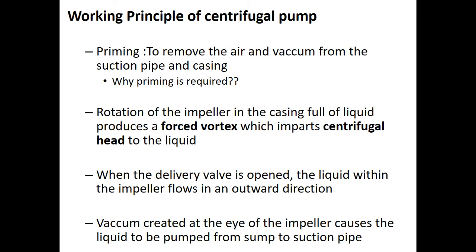If you need to remove the air, you need to remove the air from the casing. This filling of the suction pipe and casing with the liquid to be pumped is known as priming.